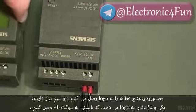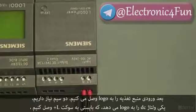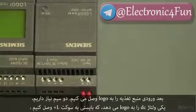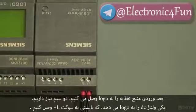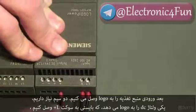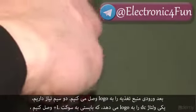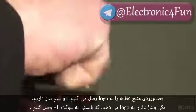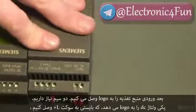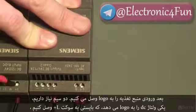Next, we need to connect the power supply input to the Logo. We will need 2 conductors. The first one will carry the isolated DC voltage to the Logo. We need to insert this conductor to the socket marked L+.